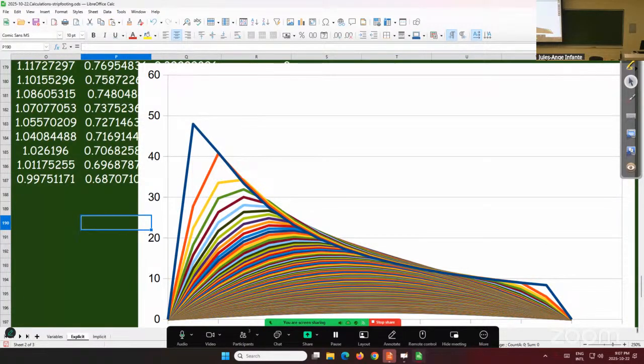The pore pressure doesn't say, oh, this is closest to me, so I'm gonna go that way. It looks, less pressure this way, so some water goes that way. It's just trying to balance it out, right? The fact that you have this asymmetry in your pore pressure distribution, the increase of the excess pore pressure is much higher here than down. So here you have this asymmetry that suddenly goes down sharply. It will distribute itself before it starts moving back here. Once the pressures get here, then it starts redistributing this way because it has moved.